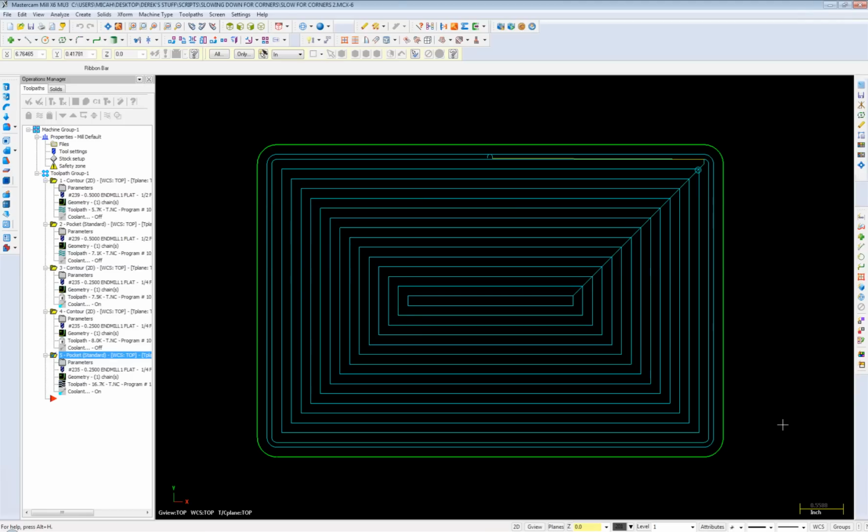I've got a question coming in from Jean. In the circle mill, the tool comes to the center before making a finish pass, and the machine makes a bad move too fast. Can we change the feed in the same way? Do either of you recognize that issue, a high feed rate with that very first move on a circle mill cut?